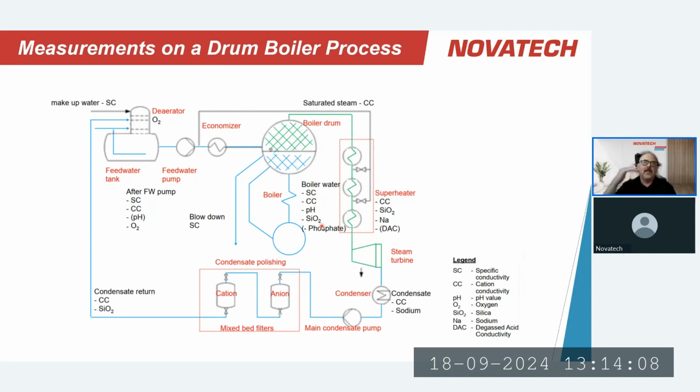Again, I'm not here to explain the reasons why those are there. We're going to talk about that in a little bit more, but in every single case, the goal is this is a potential point where it makes sense to do this measurement because of what's happening within that process. So for example, on the condensate tank, we're looking at things like sodium on the condensate condenser, because if we have a water-cooled condenser, this is where we have the possibility of introducing a leak of untreated water.